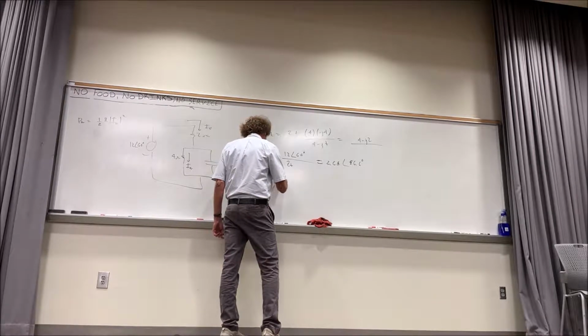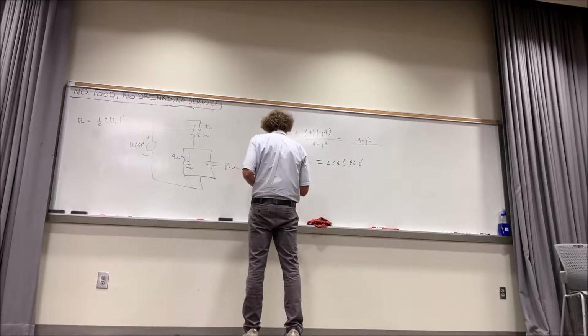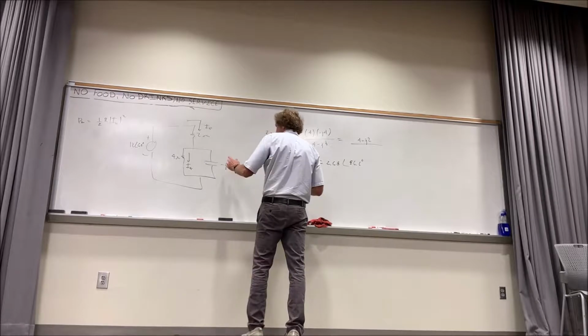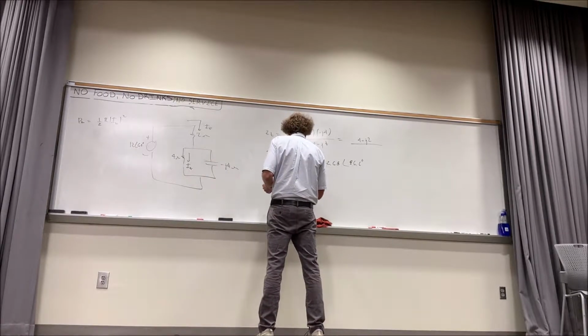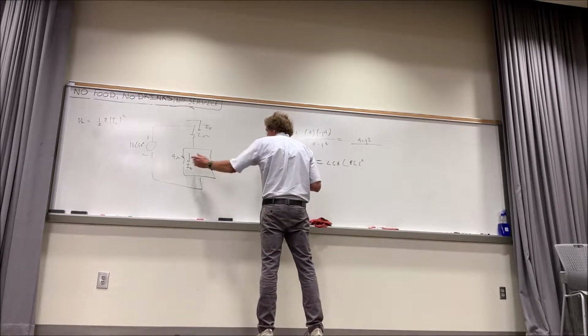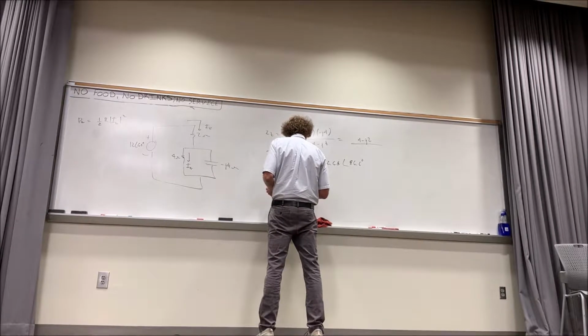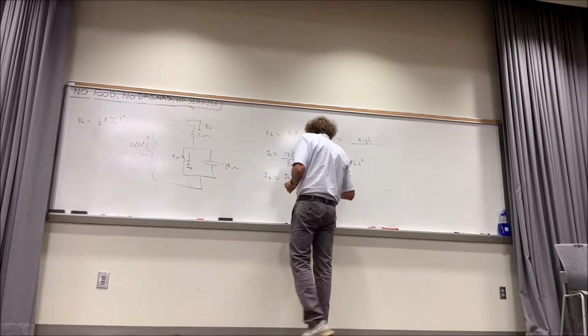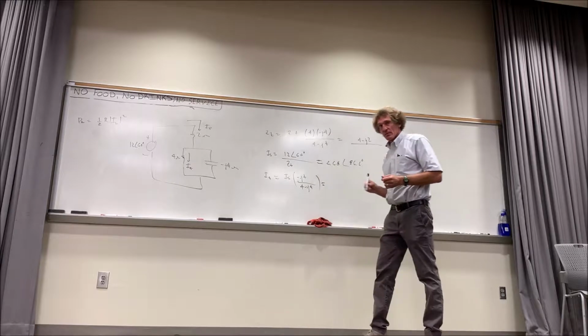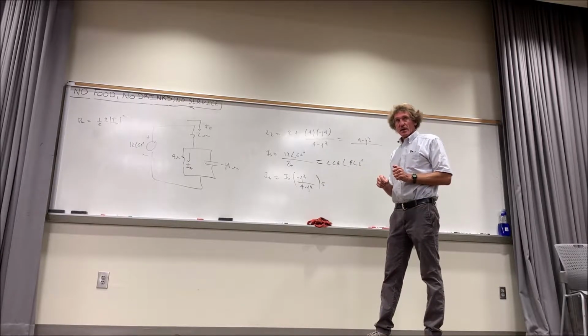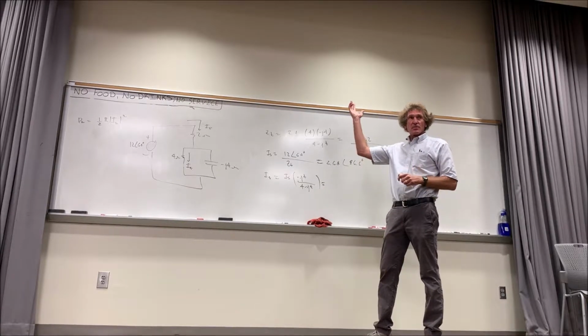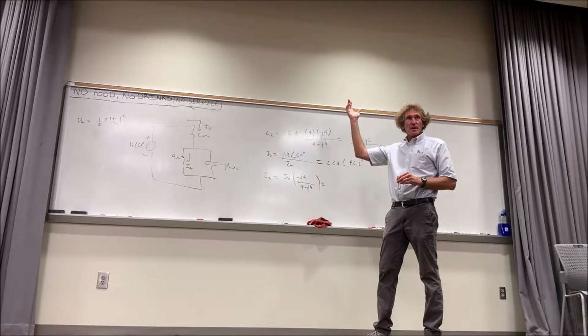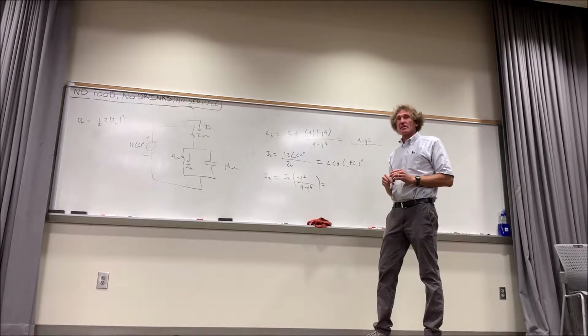I4 is equal to the total current into them, I source, times the opposite impedance, minus J4, over the sum of these two, which is going to be 4 minus J4. Do you all agree with me in class? How many understand what I'm doing here with current division? Class, do you? Okay, it's very important you have this down.